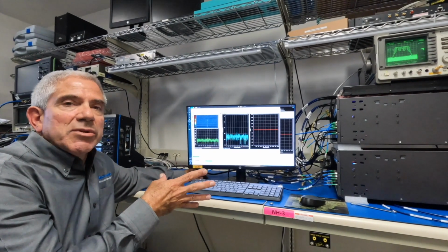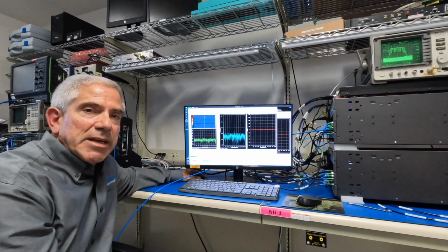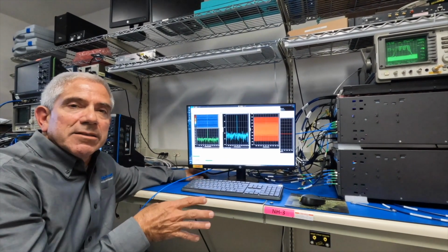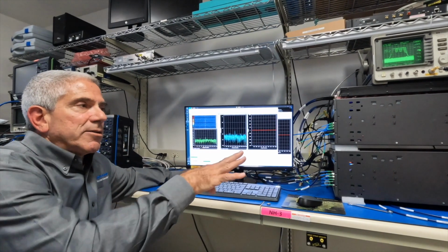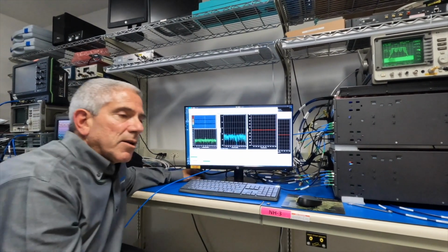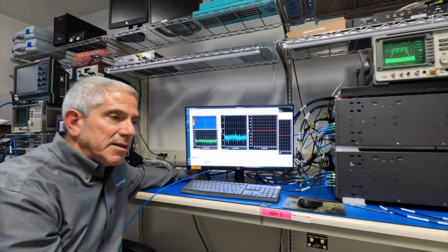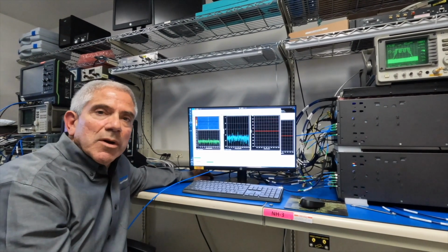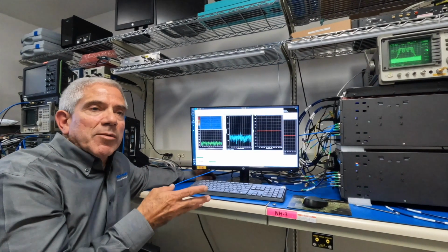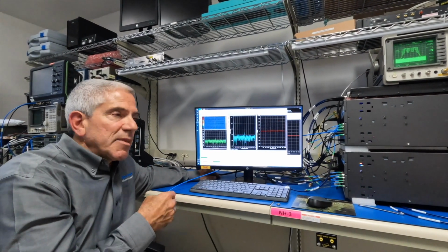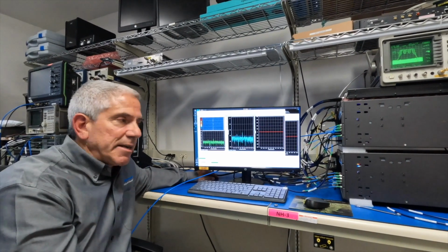So we actually sample the A to D slower than it's capable of, to stream the data to the solid-state drive RAID array that is hosted in the PC workstation that also hosts the PCIe capture cards and the PCIe playback cards. So we, again, run it at 4.8 gigasamples per second, even though it's a 6 gigasample per second A to D.